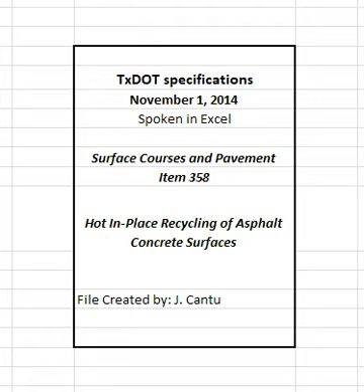Before turning the trimmed cores over to the engineer, the contractor may elect to wrap the trimmed cores or secure them in a manner that will reduce the risk of possible damage occurring during transport by the engineer. After testing, the engineer will return the cores to the contractor.